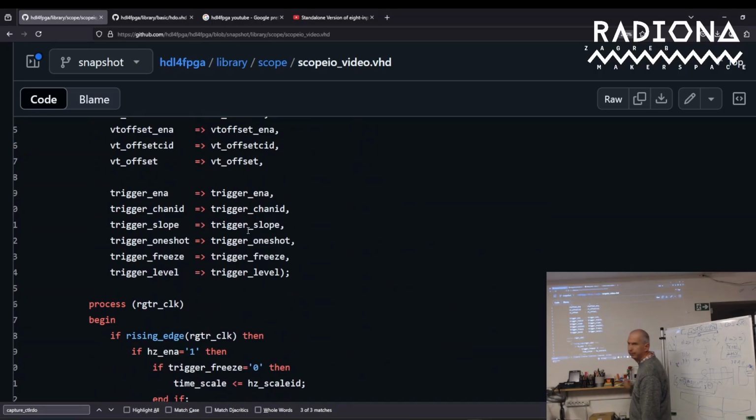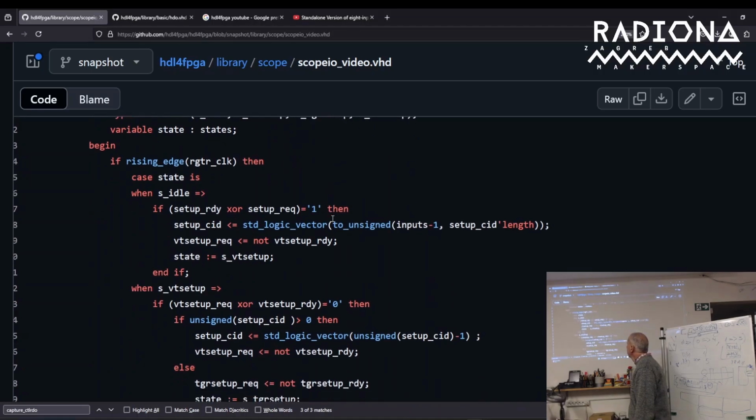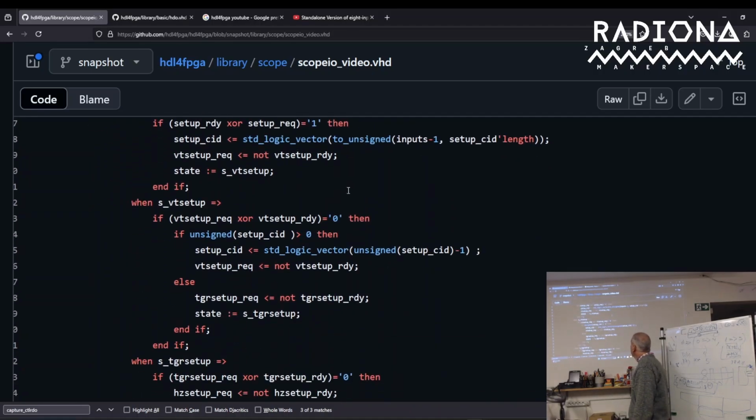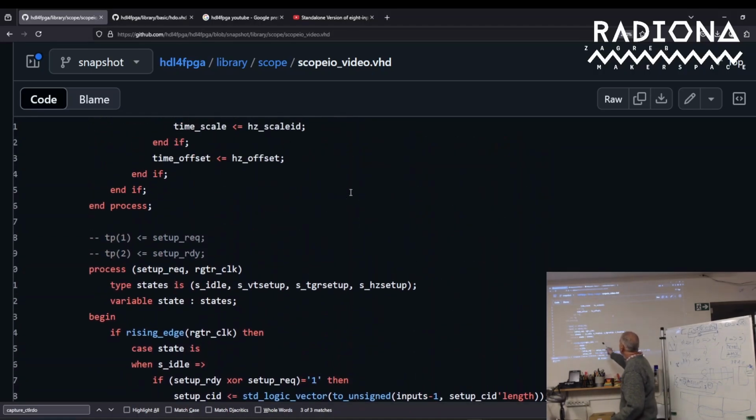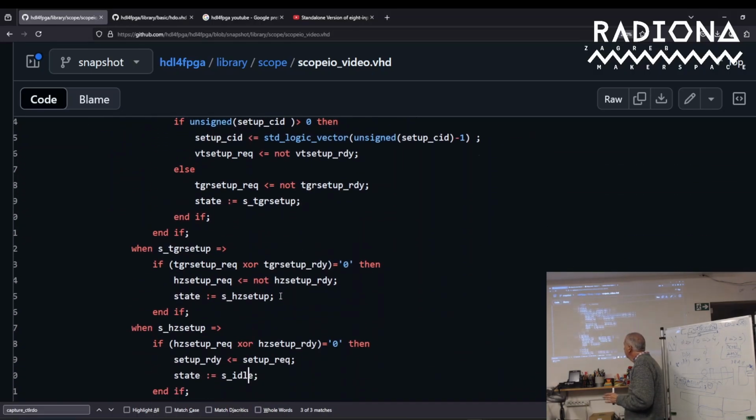So this is the state machine, how I solve the problem without a CPU. And also, if you can see, that state machine has 1, 2, 3, 4 states. So it's very simple to do. You have a controller that is maybe 2 flip-flops, no more than that. And you don't have a big state machine, because all it does is trigger another one that maybe is also 2, 3, 4 states. It's very simple for the synthesis tool to do, and it will be fast.